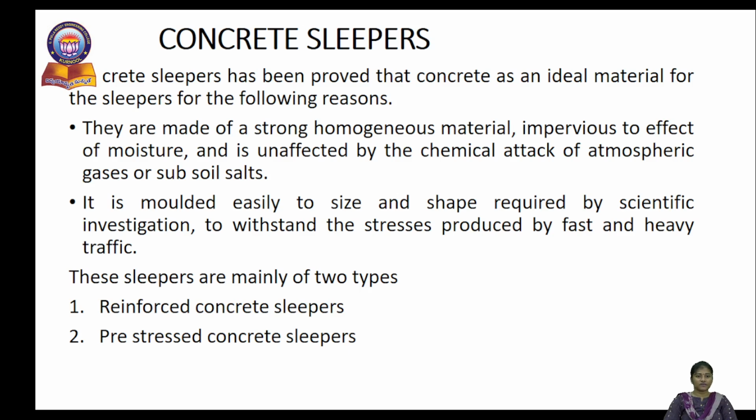Next, concrete sleepers. Concrete sleepers have proved to be ideal sleepers for the following reasons. They are made of strong homogeneous material, impervious to the effect of moisture, and unaffected by chemical attack by atmospheric gases or subsoil salts. They are easily molded to the size and shape required by scientific investigation to withstand the stresses produced by fast and heavy traffic.